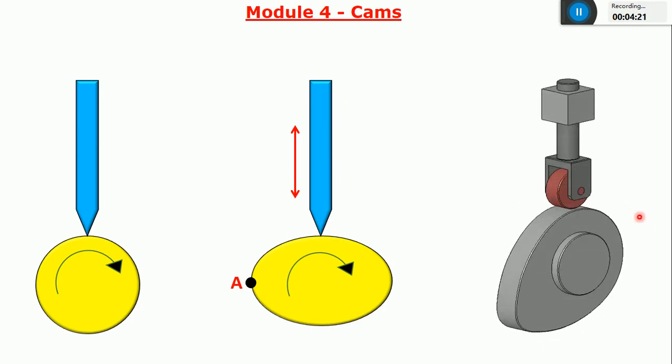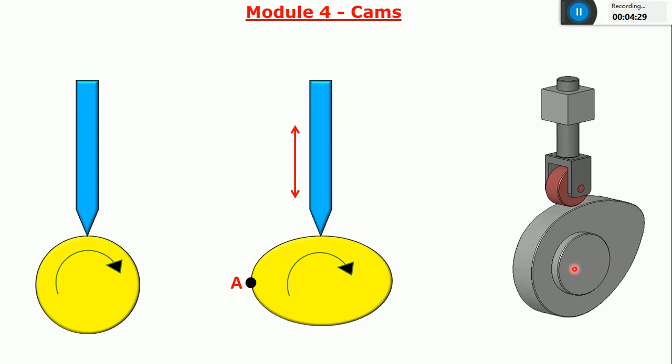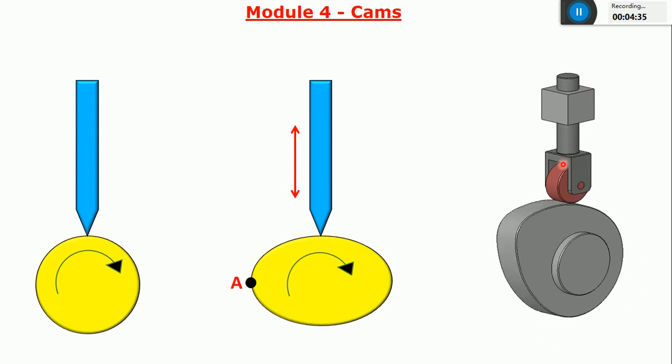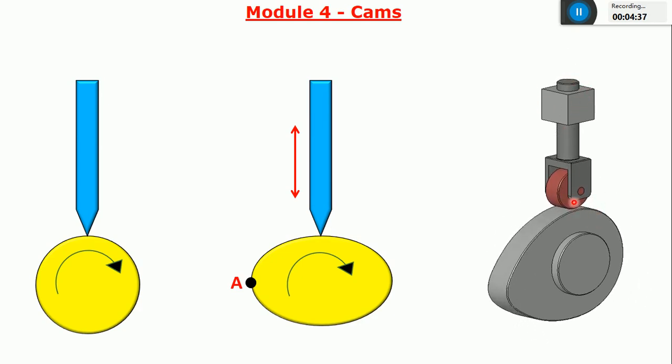So in the animation you can see, this is nothing but a cam which is connected to a camshaft, and again it is connected to a motor. The type of input motion is a rotary path. And you can see this is a follower, and there is no joint between the cam and follower. Simply there is a point or line contact between these two elements.